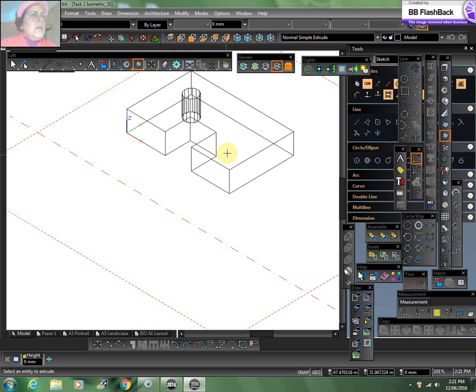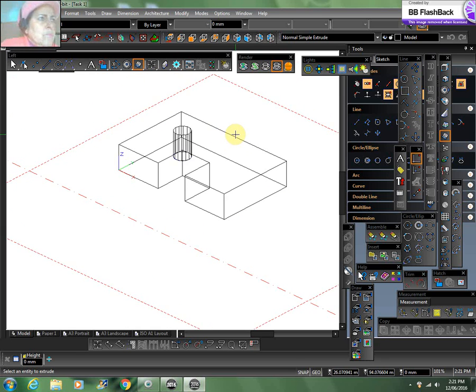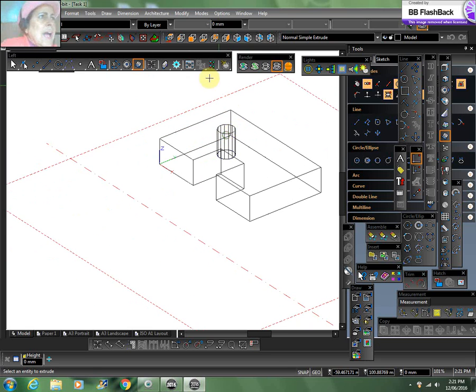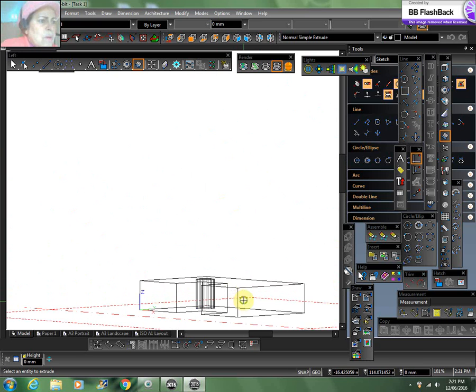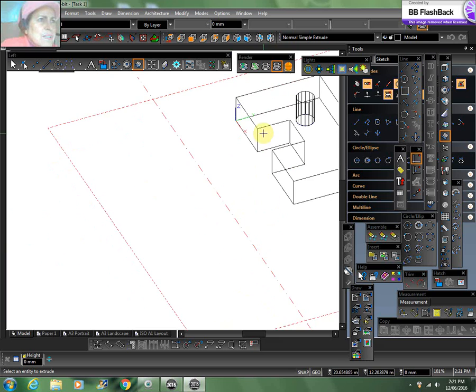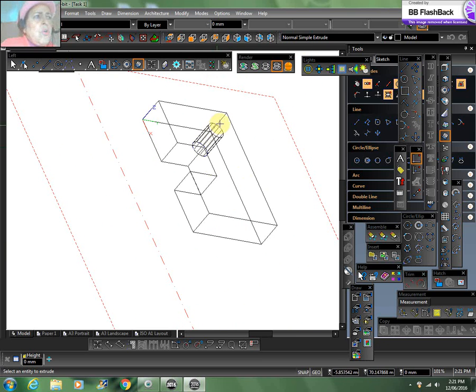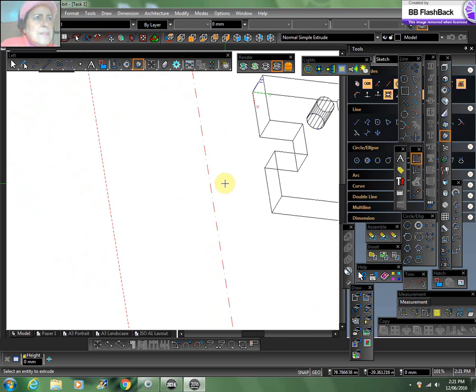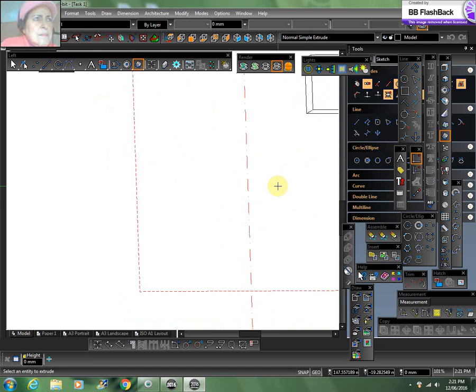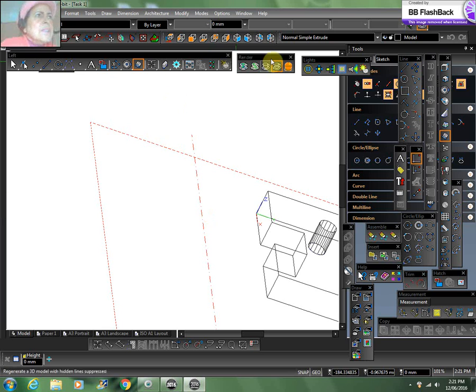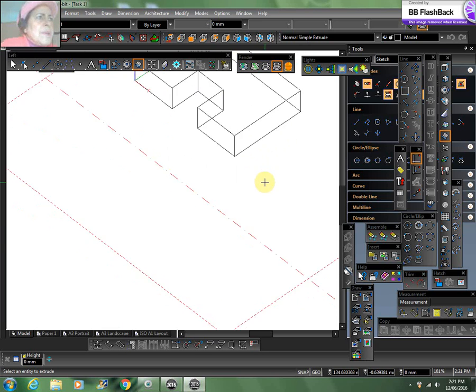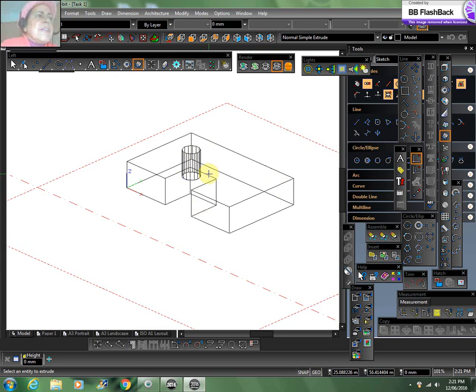I have done this before, and you can see I hold the wheel of the mouse. If I turn this upside, you see the hole? You see the hole is created. If I turn this a little bit like this, you see the hole completely. So I press southeast, so it sits on its plane like this. This hole will be created, and that is called extruding downwards. That is a hole. There are other ways of creating a hole by Boolean facet tools and 3D subtract. That is not the subject of this lesson.